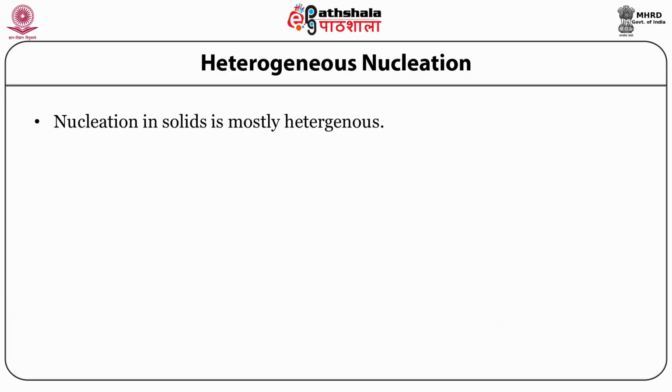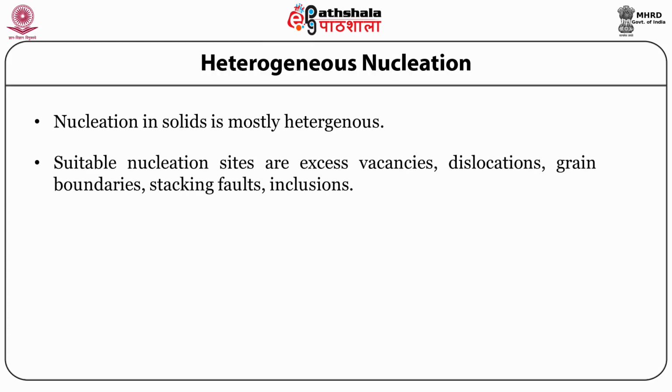In materials, whenever there are suitable nucleation sites present, like excess vacancies, dislocations, grain boundaries, stacking faults, inclusions, nucleation preferably occurs over there.